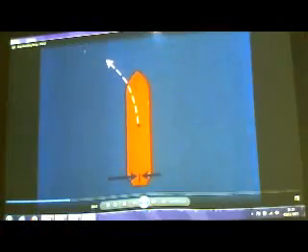In most cases, the helical flow from the propeller does not strike the rudder uniformly. Here on the starboard side of the rudder, the flow is straight and fast at the bottom, but slow and unsteady at the top, thus reducing the pressure on the rudder in this area. Using a mirror placed on the far side of the model, the port side shows no unsteady flow, and therefore no reduction in pressure. The pressure on the rudder shown by the blue arrows is higher on the port side. This will tend to cause a gentle turn to port.